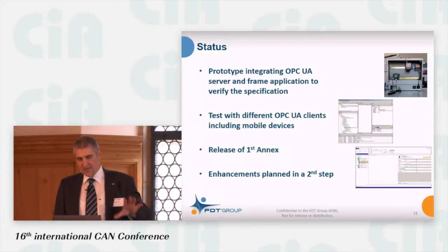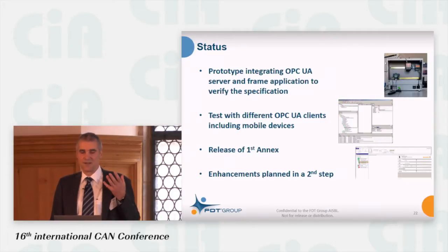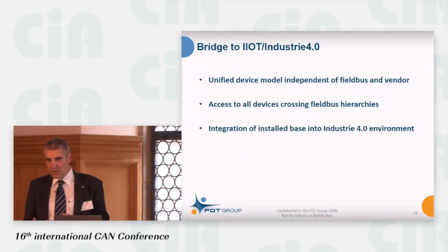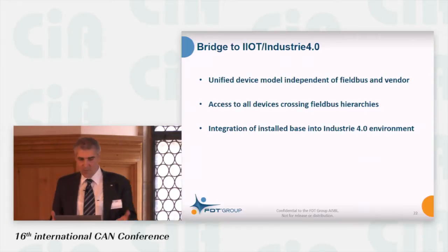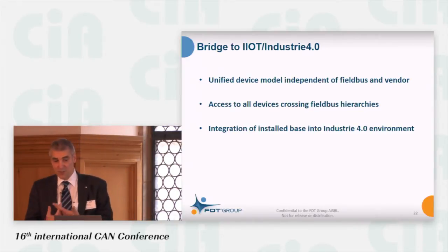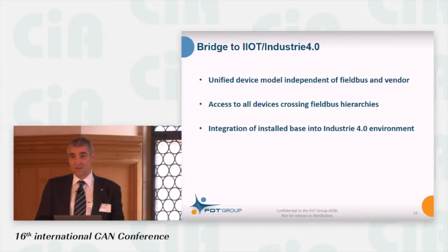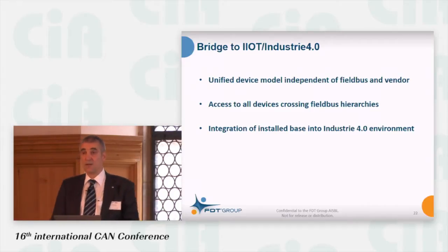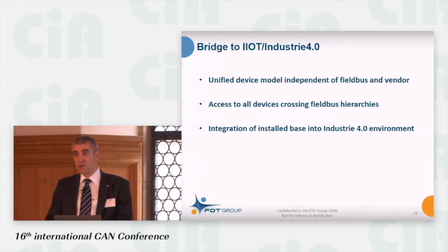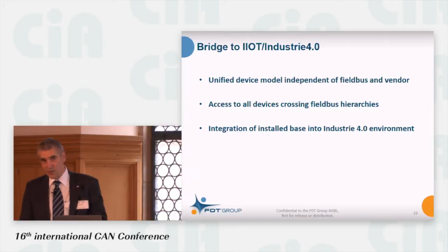And as I said at the beginning, what we achieve here is a unified device model for an OPC UA client, independent of what field bus the device is on and from which vendor this device is. When you look today at all the OPC UA definitions, each field bus organization is doing its own OPC UA model.